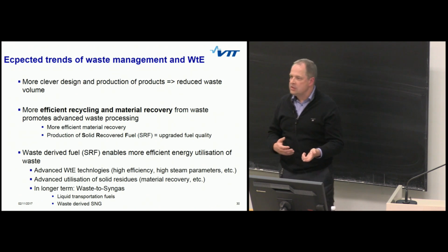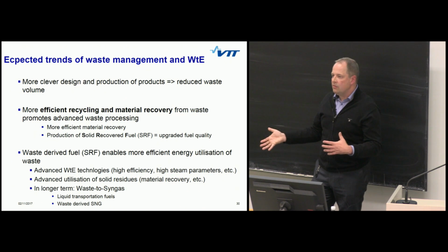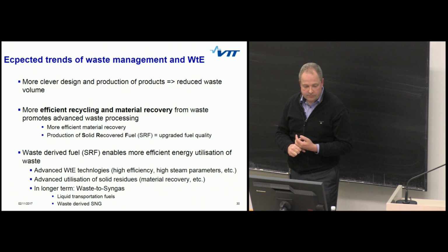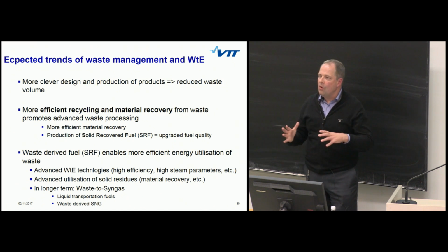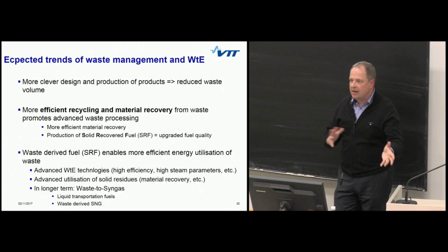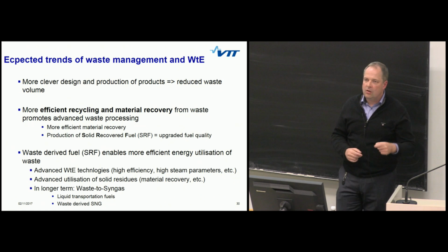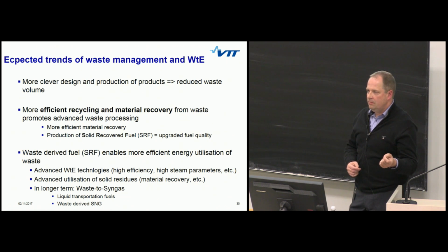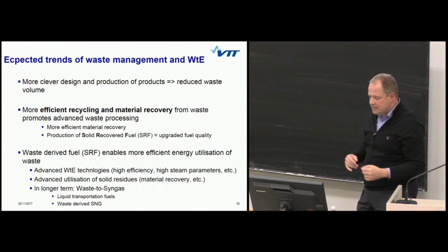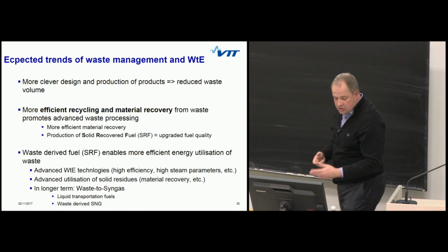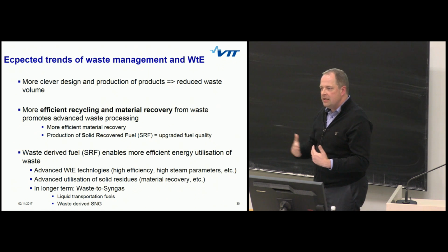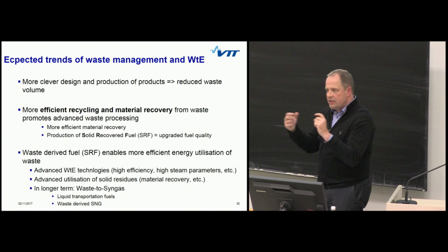So this gives again a possibility to decarbonize in some countries, for example, cement production, which is one of the biggest CO2 emitters in this world. And of course, when you have more standardized fuel, you know that your specs in regard to alkali etc. are within certain tolerances. You can then also go for higher steam values, because you don't have to worry about the corrosion anymore. You know where you stand, and then you can get into improved technologies, and you can also get a better energy efficiency out of your system. And also the SRF is really a commodity in a way that you can sell it, you can buy it, because there's a standard that says what it should be.